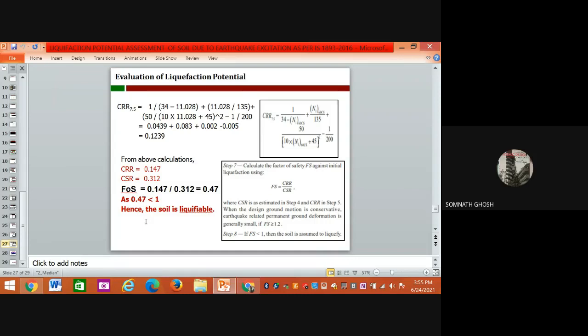So basically, I tell you that for the shallow foundation, generally it is not giving trouble, but for piles, in many situations I found that the in-between layers are extremely bad, but we are not considering that, and the pile capacity we are showing very high. So these are the things you have to keep in your mind.